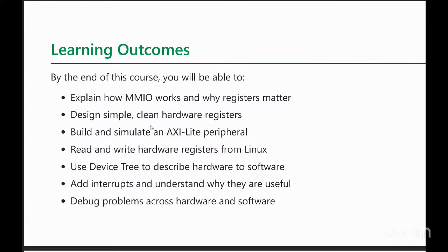And then we're going to study the registers, that is memory-mapped IO, how we're going to read the content from the memory-mapped location, and similarly how to write into a particular register. These things are supposed to be controlled with the help of the operating system Linux. Then we're going to increase the level of coding with the help of the device tree, which describes what things are there in the hardware, how it is going to interface, and at which location. All these fundamental software-level device tree mappings we're going to discuss.